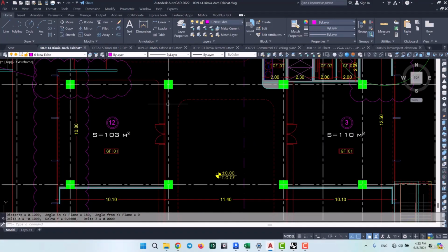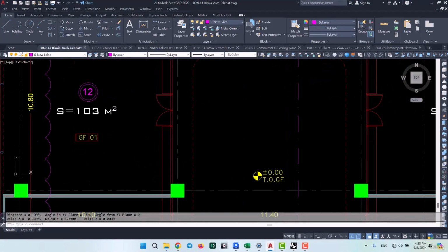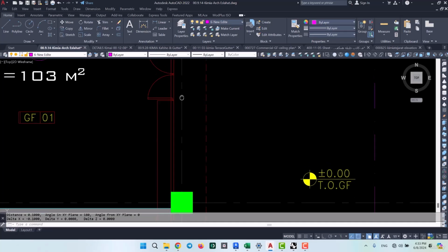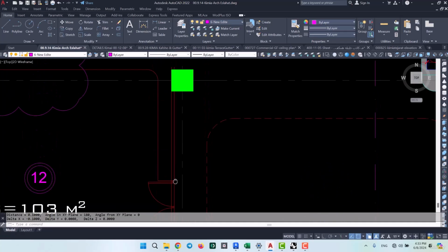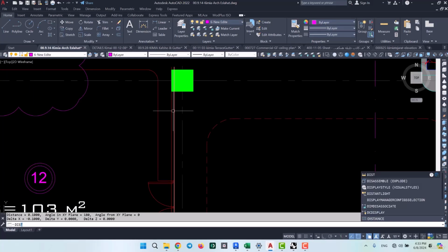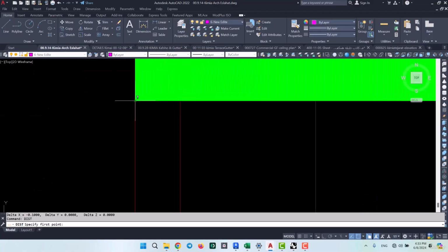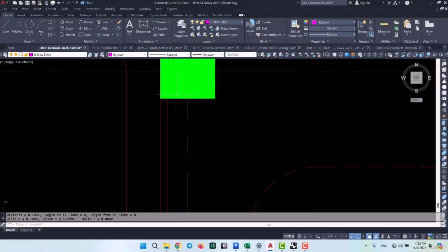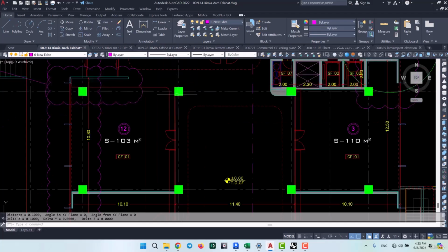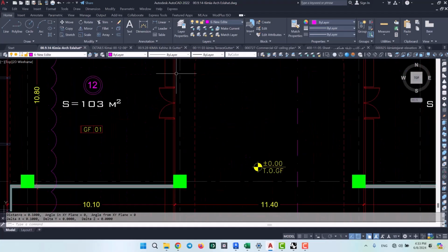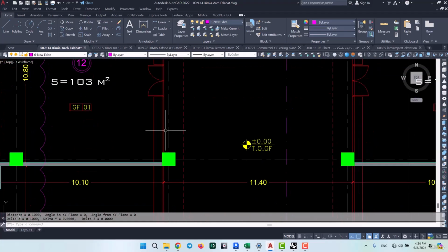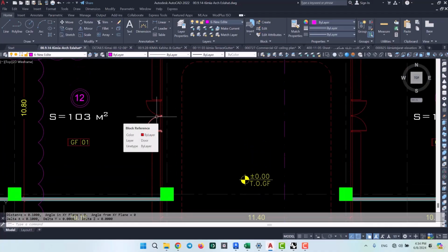As you see in this Phase 1 CAD file that the client has given to us, the drawing seems very simple, only there's going to be this door that we need to place. And also, if I try to measure the distance for this part, and check for instance from here to here, we will see its thickness is 10. So there's going to be some 10 centimeter thick partitions. So now we could very easily go ahead and place some 10 centimeter thick partitions over here. And we're going to make them of the glass type, give them some mullions. And also we're going to need to place the door panels for here, followed by the actual door family that we will be placing later.